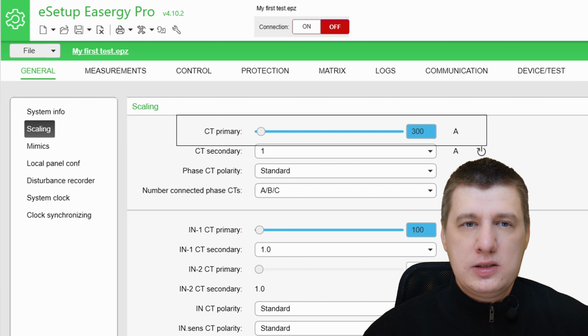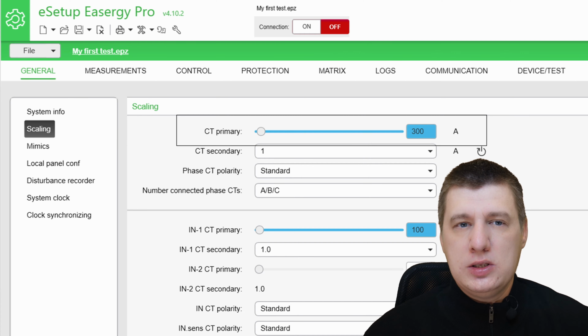For example, 300 settings. If you have current transformers with a ratio of 300:5, you must configure the relay with a CT primary of 300 amps and a CT secondary of 5 amps. The ratio tells the relay that every 5 amps it feels at its rear terminals actually represents 300 amps flowing through the primary power line. If the relay measures a secondary signal of 3 amps, it uses your settings to calculate the primary value.